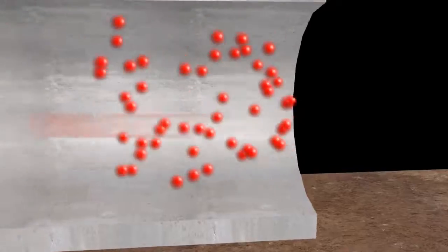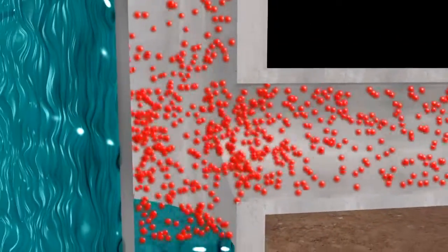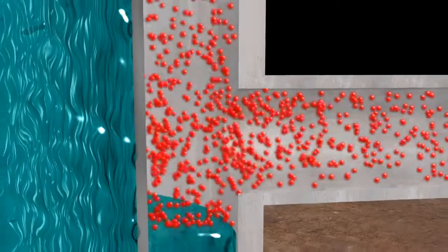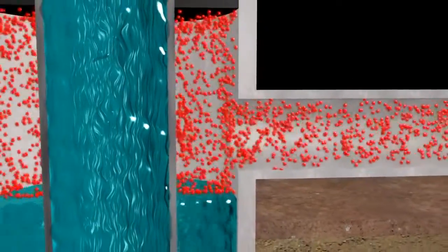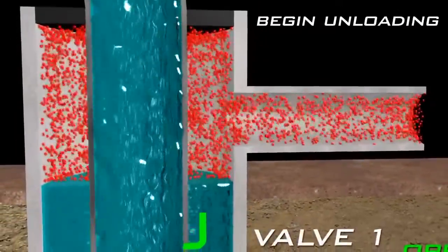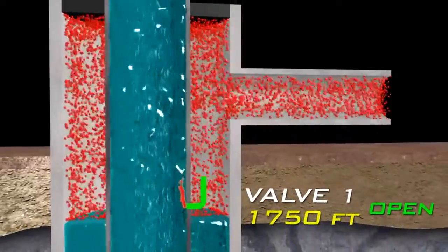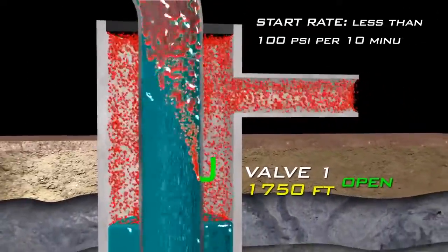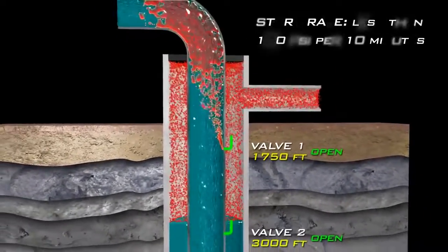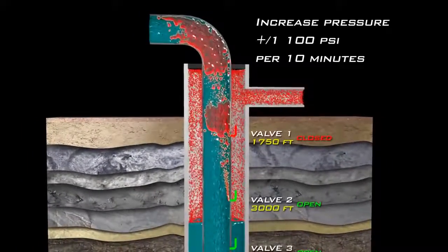When gas injection begins, the fluid levels in both the tubing and annulus are at the surface. The pressure of this fluid holds the valves open. As the gas is injected down the annulus, fluid from the tubing and annulus are being U-tubed through all valves. The annular fluid unloads past the first valve, and the gas injection aerates the liquid above the valve, decreasing its density. As the fluid continues to unload below the next valve, the gas injection transfers to that valve.